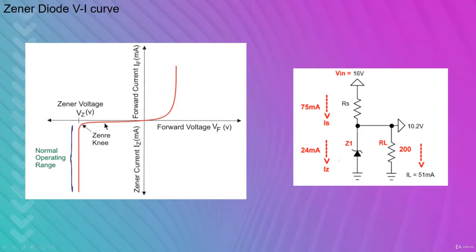The Zener diode has a well-defined reverse breakdown voltage at which it starts conducting current and continues operating continuously in the reverse bias mode without getting damaged. As the reverse voltage increases to the predetermined breakdown voltage, a current starts flowing through the diode, and the current increases to a maximum which is determined by the series resistor, after which it stabilizes and remains constant over a wide range of applied voltage.